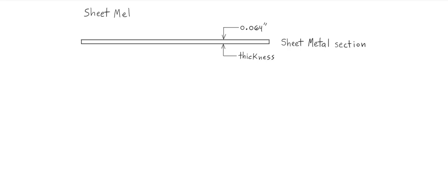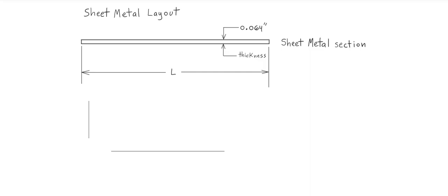So there's a certain U bracket you are bending for, let's say, an APU mount with respect to aircraft sheet metal structures. And so you must calculate the length of the sheet metal section, the linear measurement. And so the finished product is a U bracket.